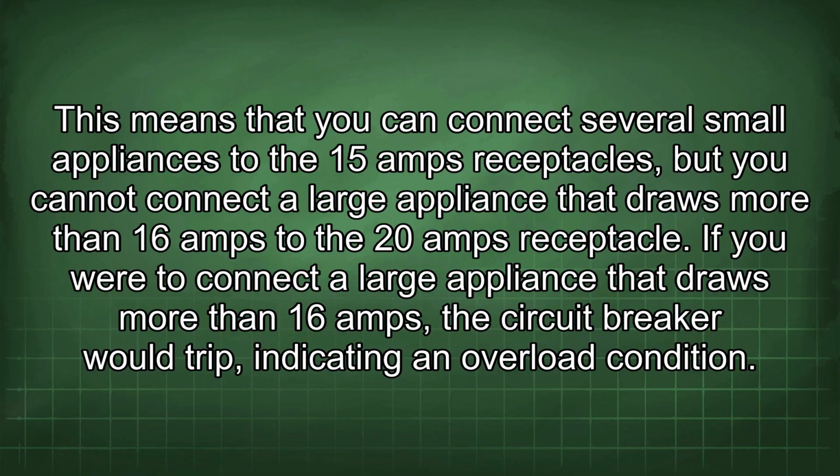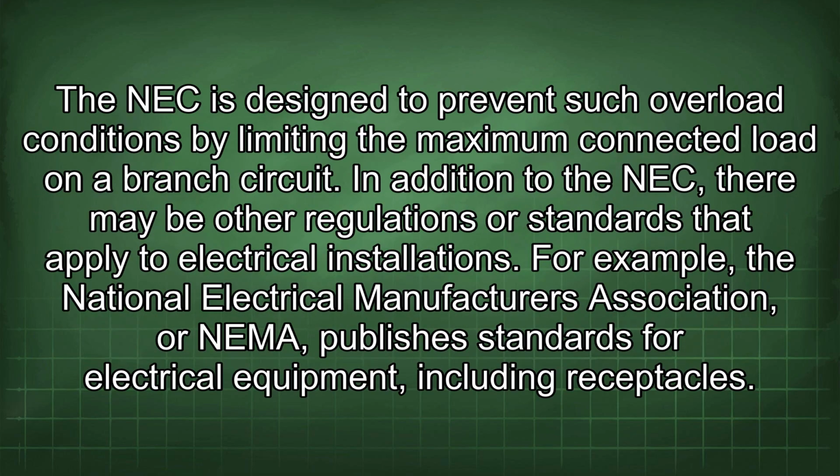If you were to connect a large appliance that draws more than 16 amps, the circuit breaker would trip, indicating an overload condition. The NEC is designed to prevent such overload conditions by limiting the maximum connected load on a branch circuit. In addition to the NEC, there may be other regulations or standards that apply to electrical installations.